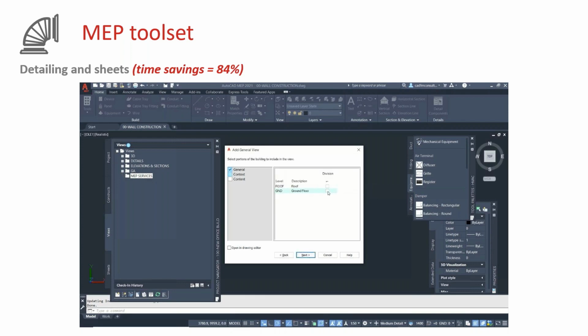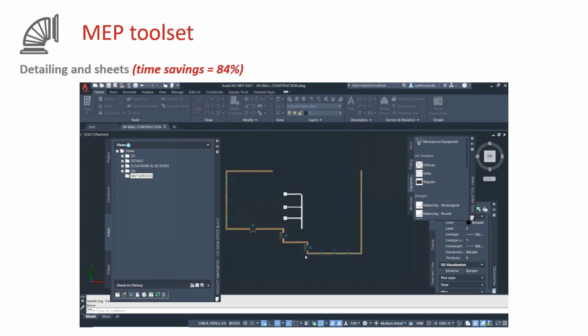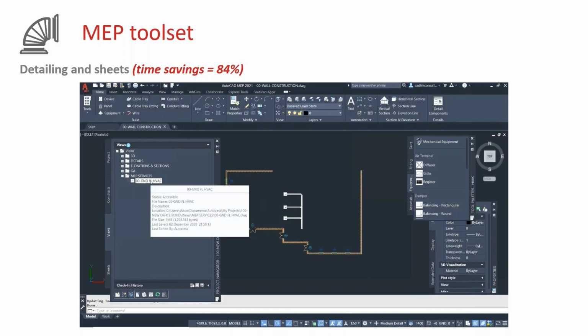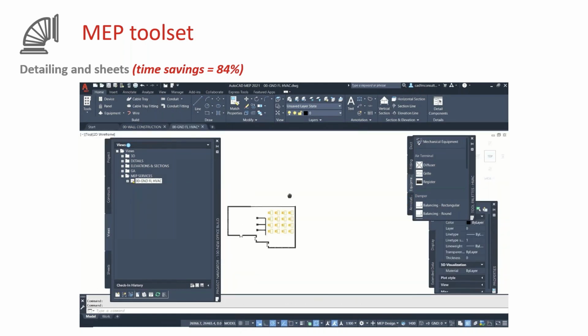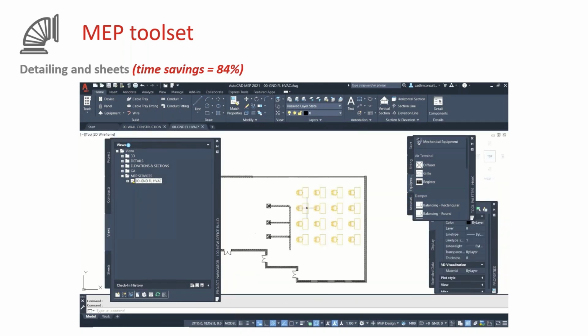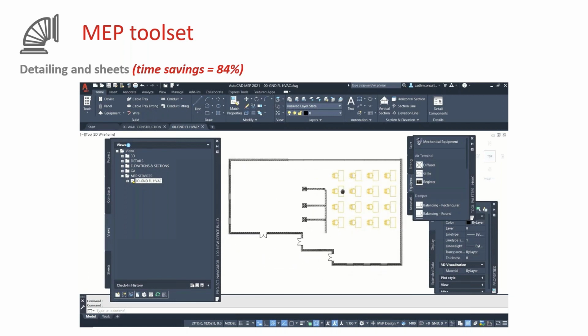And then we're going to apply to only have the elements of the building on the ground floor to show this. So we're going to have the curtain walling, furniture fit out, and the wall construction. We don't want the roof in the way because we won't be able to see it. So I'm going to click on finish there, and that's now created a new 00 ground floor HVAC view there, as you can see. And when I double click on that and open it up, it opens up a separate DWG file. So we've created there a new DWG file with the information we want to show.